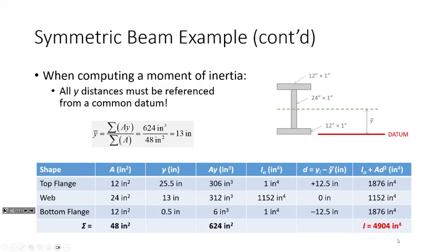So for the bottom flange, 12 times the height cubed over 12, right? So 1, because 12 times 1 cubed over 12 is 1. Same thing for this and this. For the web, it's the base times the height cubed over 12. So it's 24 cubed over 12. 24 cubed over 12 is that. With me so far? So that's the moment of inertia.